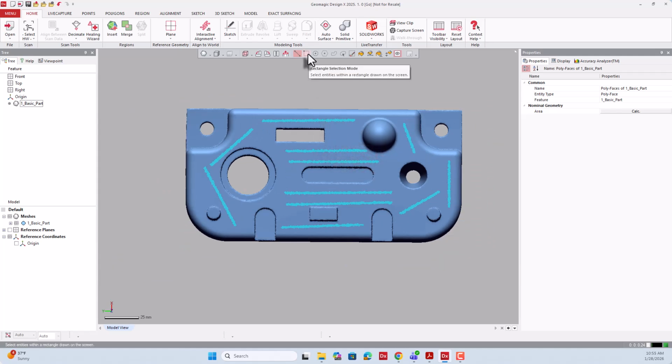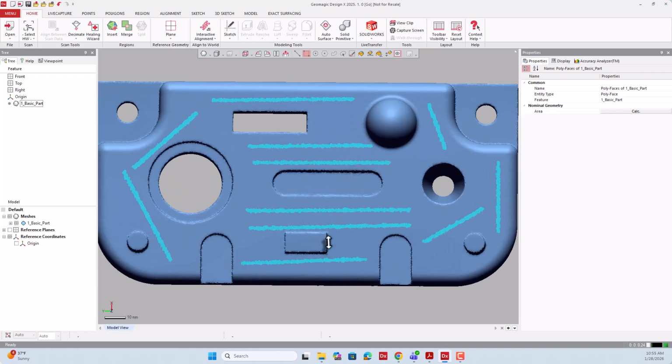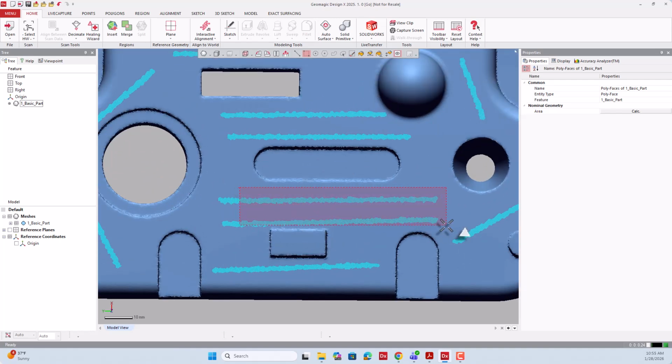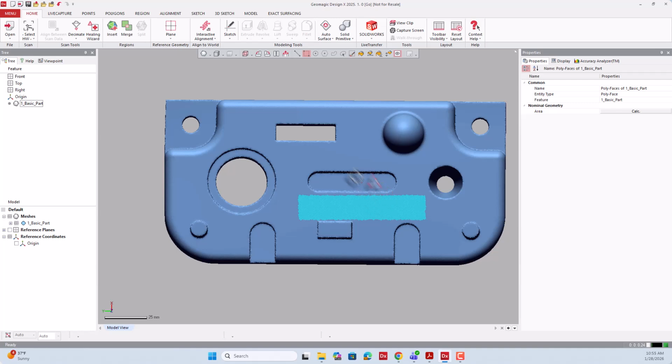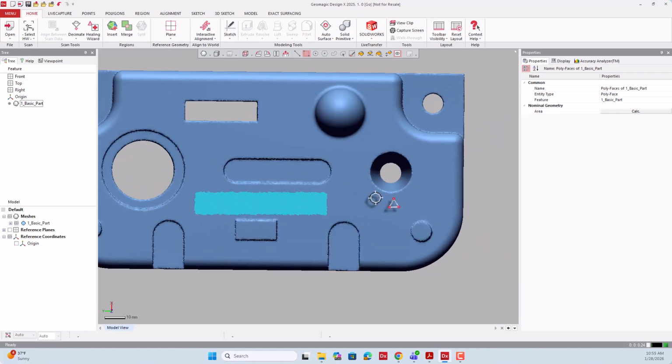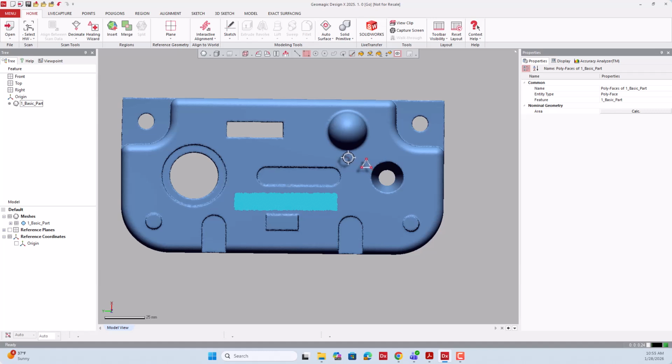And the next mode is the rectangular selection mode. This operates in the same way. So you can make a drag box and it will select all the triangles on that particular drag box that you made. So you can click, make the drag box and drop it. Like that. Click, make the drag box and drop. Always the selected icons would be shown in a turquoise kind of a color, and the same key applies here too. So if you want to add to your selection, you can hold Shift and you can add to your selection this way.